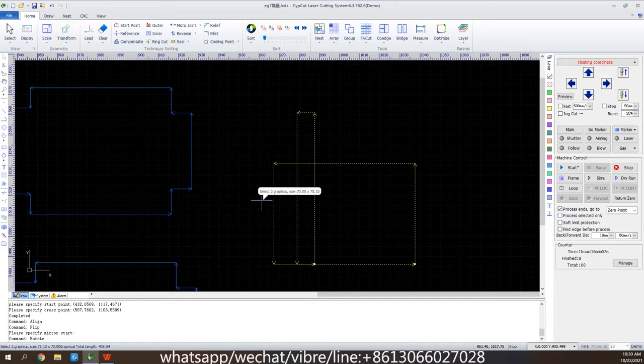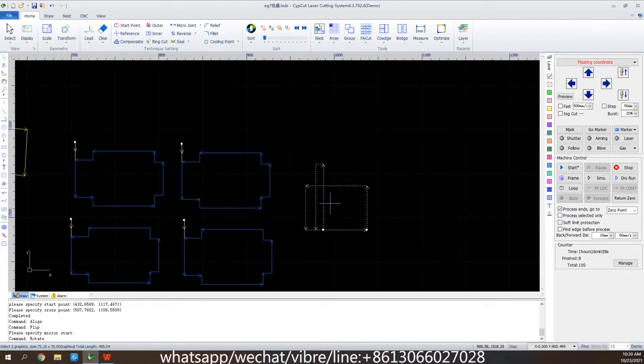And when we laser cut parts, we make the cutting path start from several millimeters away from the part. This way it could get cut much better. The distance is what we call the lead.